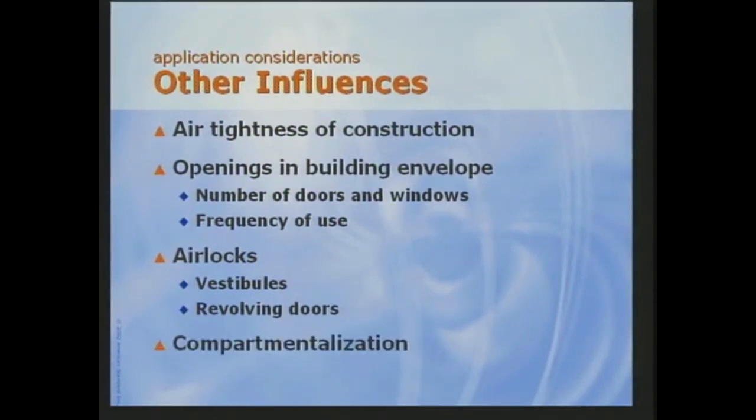Finally, compartmentalization. Stack effect pressure can be greatly reduced by breaking the building up vertically into shorter pressure compartments. Floor-to-floor air seals and floor-by-floor air handlers can be keys to good compartmentalization.